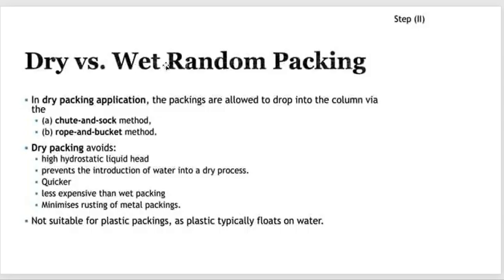You bring the tower and fill the tower with clean condensate. Then you empty the bags of the Raschig ring, for example, inside this clean condensate, with the elevation and the head. When you fill the tower with this Raschig ring, you start to withdraw the clean condensate. Then you will get your Raschig rings stacked layer after layer inside the tower. This is named the wet installation process.